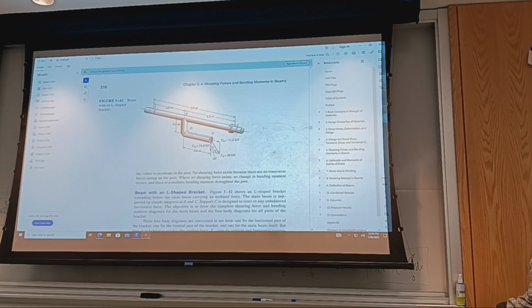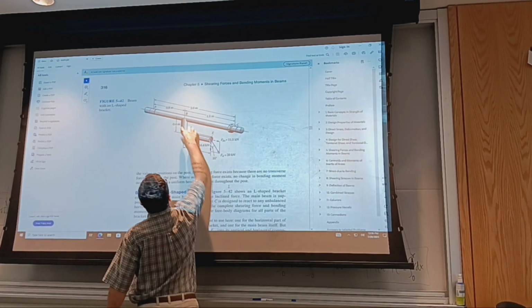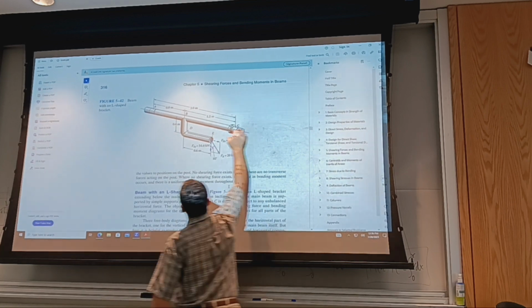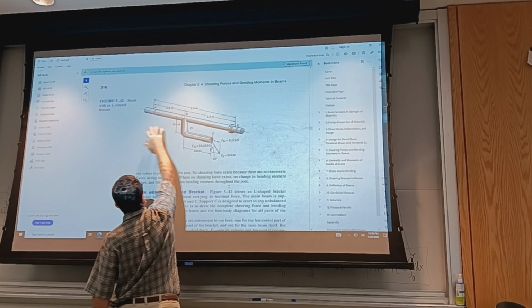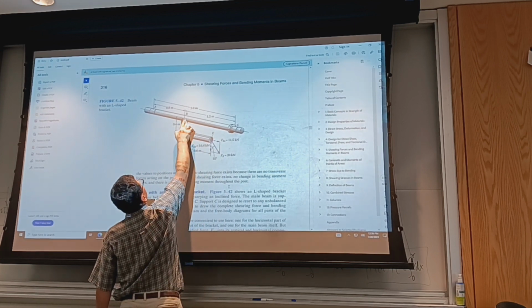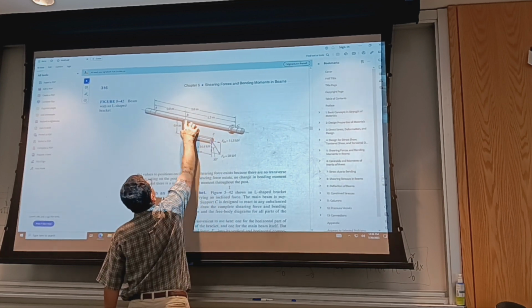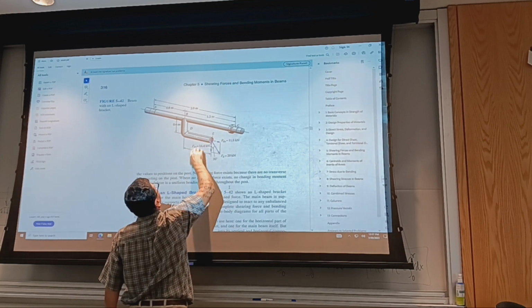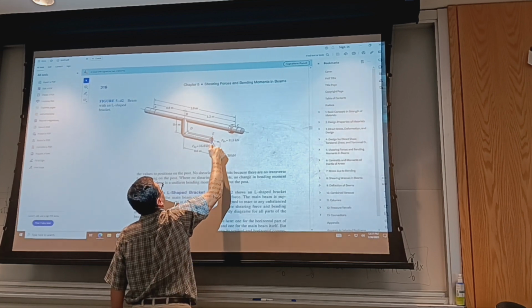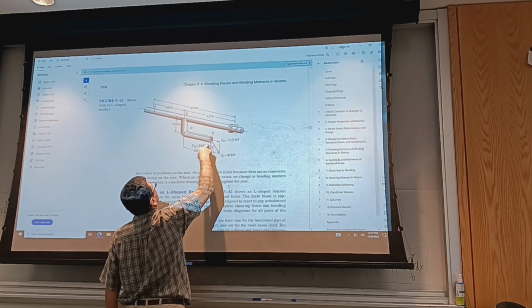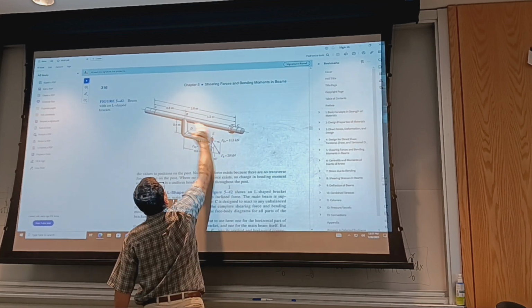And another example, and this force is at some angle. And we isolate, could be just this piece, or if we want to analyze, we go in steps. So I analyze this one, and then the rest of it. Or if I'm interested just in the big piece, the long horizontal piece ABC, what is delivered to it from this L-shaped piece. So I see this same force there plus the corresponding moment. So if I move the force elsewhere, I need to add a moment, because it wasn't along its line of sliding.